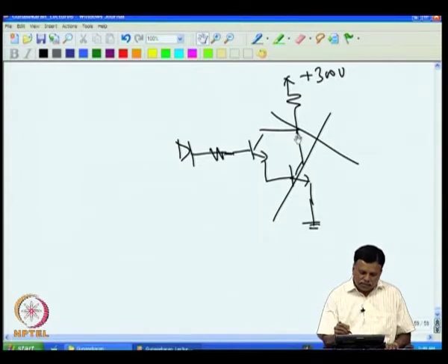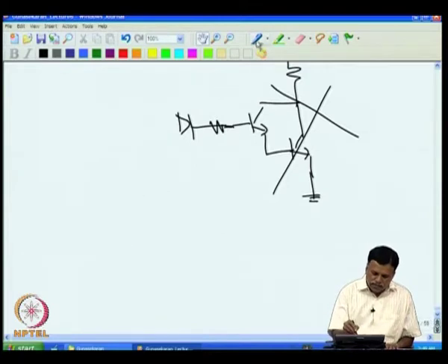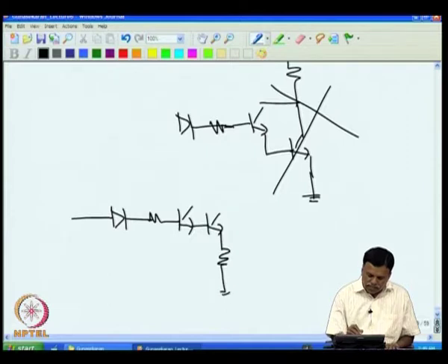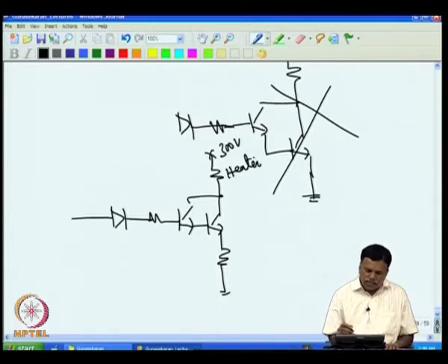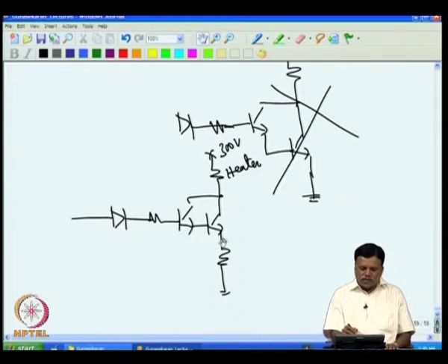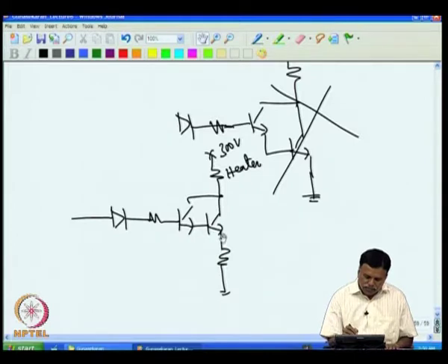So if you want that to happen, then we have to modify this circuit. Now, one simplest way of modifying this would be to pick up the thread from the output of the error amplifier. Then, one simplest way could be, I can have a resistance here, then have a heater here. In this circuit, we had used this resistance. Assume this base current is negligible. If the base current is negligible, then I can assume there is no voltage drop here, and if, for example, 14 volt is present at this point, we know at this point you will have 14 minus 1.2, that will be 12.8. So the current through this is now determined by this 12.8 divided by this resistance.